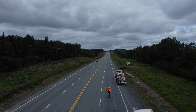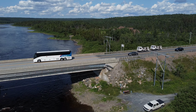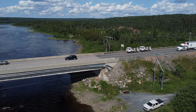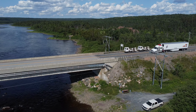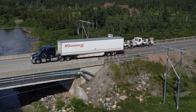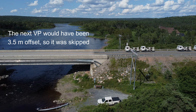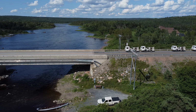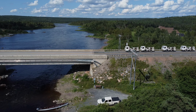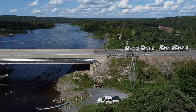But what was interesting about working on the Trans-Canada was there were certain places where there were certainly structures of interest. And here we're moving up towards a bridge abutment. We stayed back with the sets of vibrators from the nearest pad, 16 meters, and we would have anticipated the vibration to be about 2 millimeters per second at 16 meters offset. So we had two sets of vibrators. The front set were shaking all the odd stations, and the second set in the back were shaking the even stations. So they were staggered working up the highway.